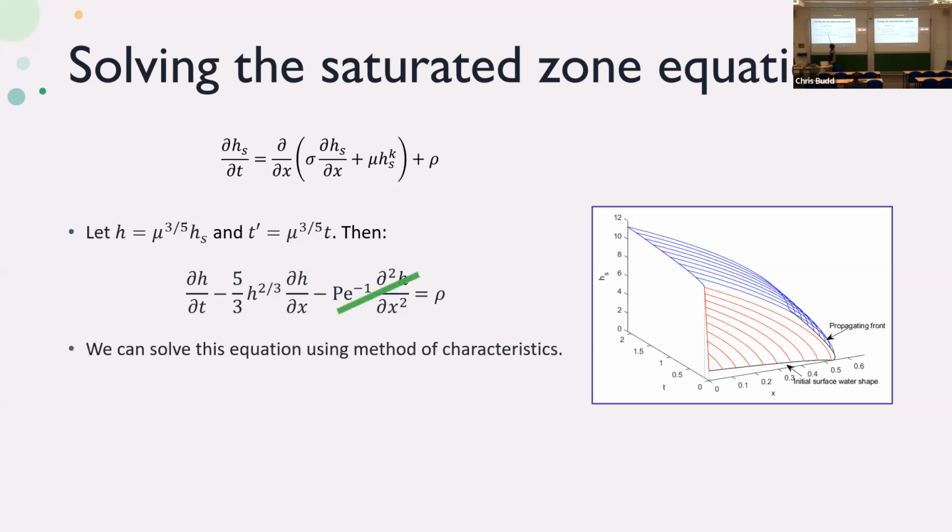What I'm left with is a first order, non-linear PDE, which can be solved using the standard method of characteristics, in which the characteristic lines will start either from the initially saturated zone and will rise because of the increased rainfall, or will start from the propagating flow, which is slowly moving to the right, away from the river.